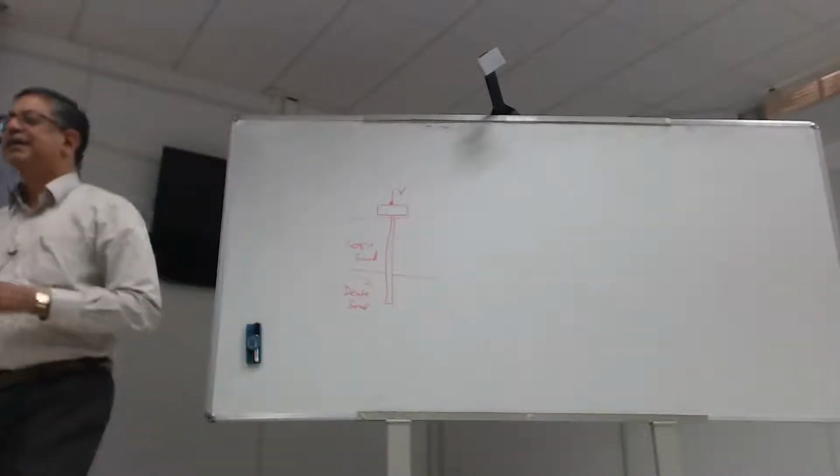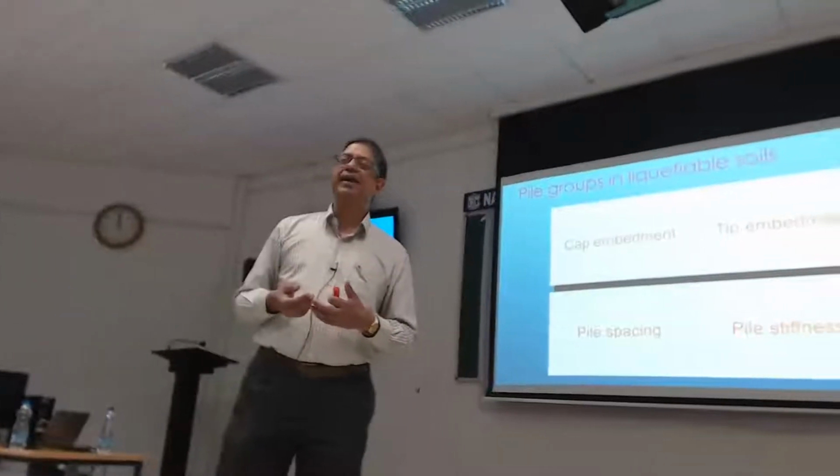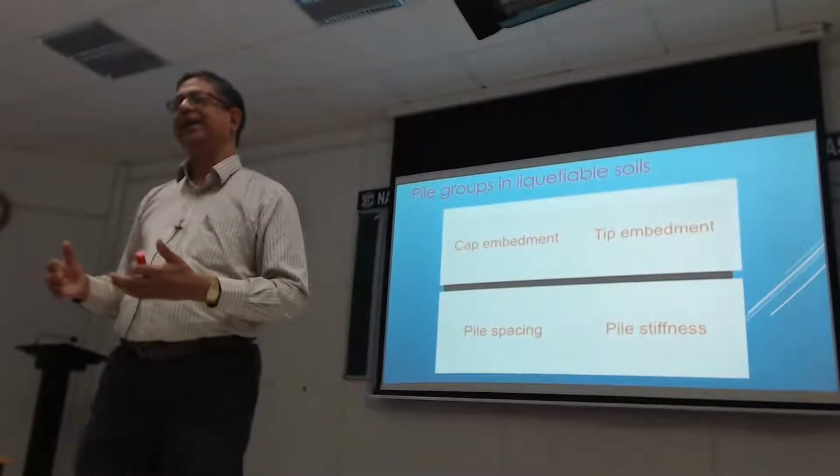What we know is even in dense sand, at 90%, 85% relative density, you will get significant pore pressure buildup. Okay? So from a pore pressure point of view, loose sand produces positive pore pressure, dense sand also produces positive pore pressure. Okay? There's one main difference by which you can tell them apart. One is what the loose sand does in this high pore pressure environment when it's liquefied. The dense sand tends to dilate much more strongly when you shear it compared to loose sand.